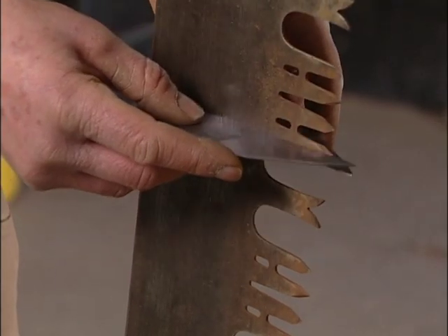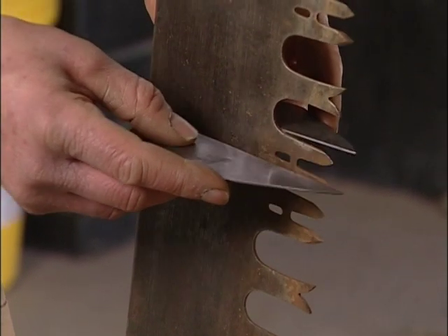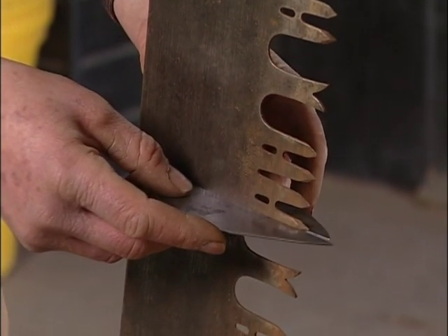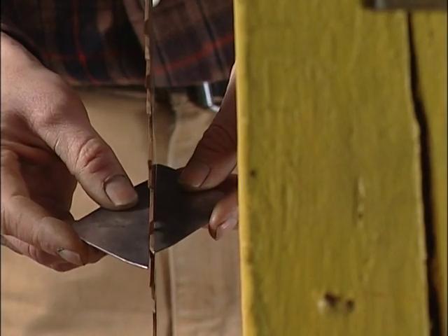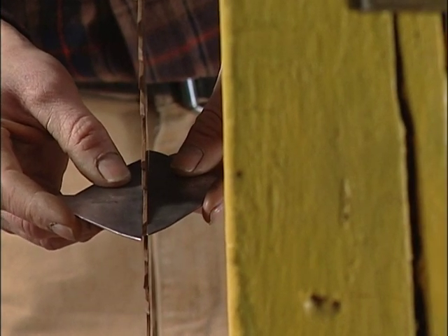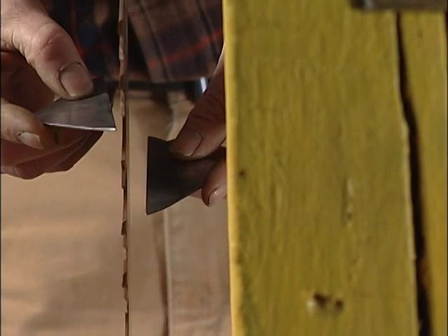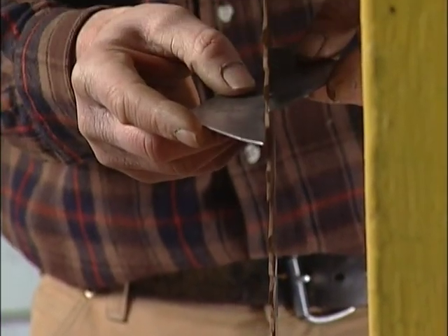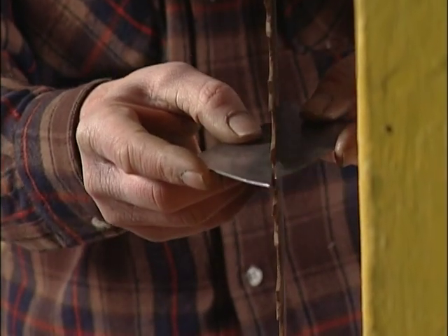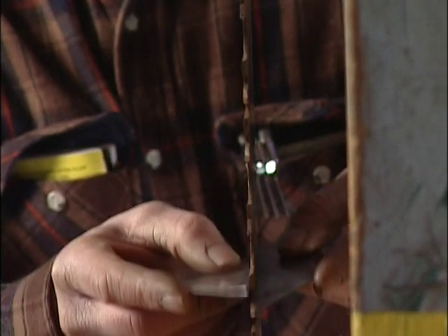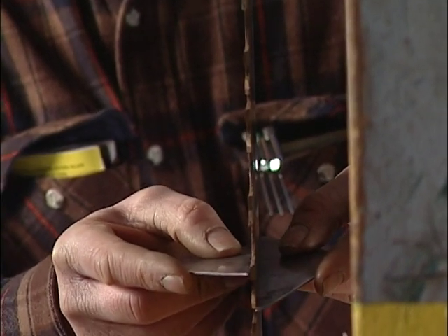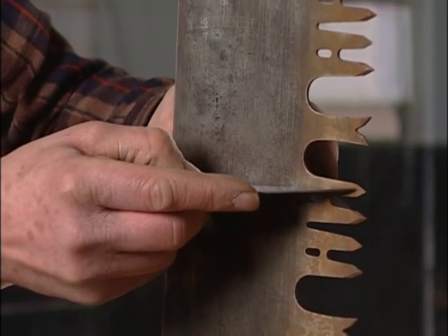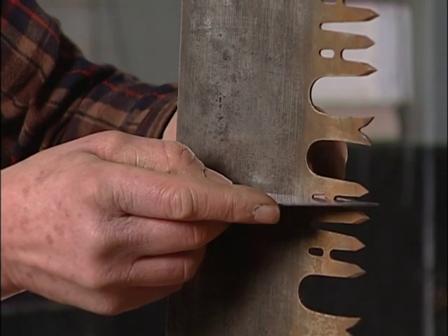Another thing that you check for as you're running up the saw like this is a bent cutter tip. Because of the set, each cutter will slightly hit the straight edge, but if you have a cutter which for some reason is bent considerably out of line, you'll become very quickly aware of it. It just hits the straight edge a lot harder. Here's actually a tooth that's hanging up more than the rest of them were, so this one is bent out of line a little bit more than it should be.